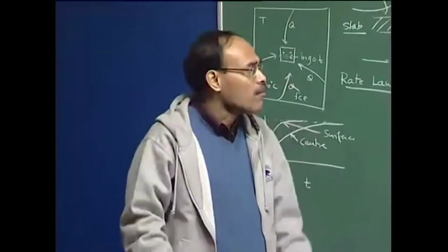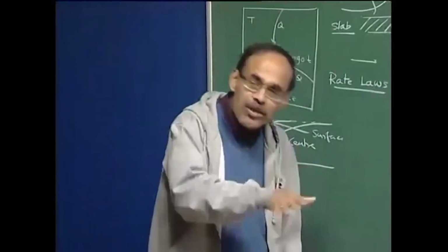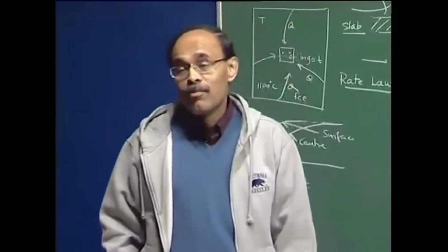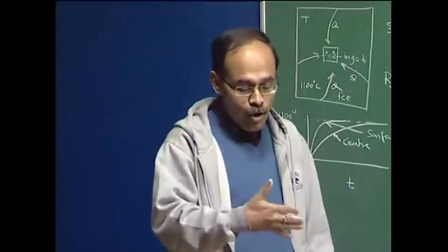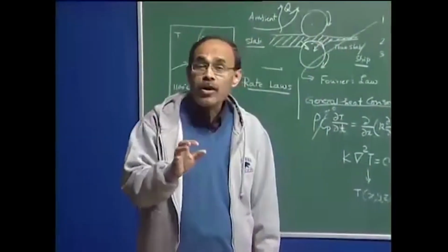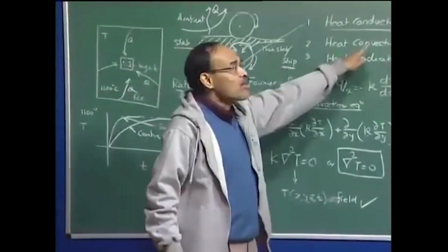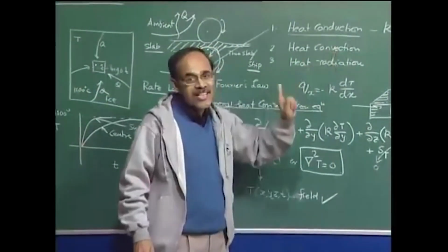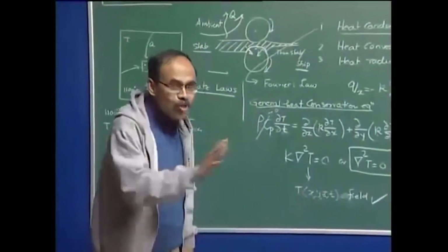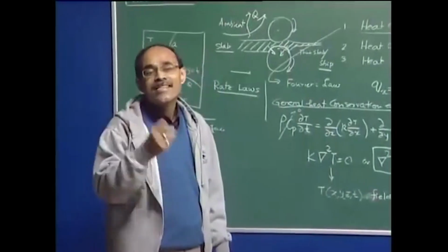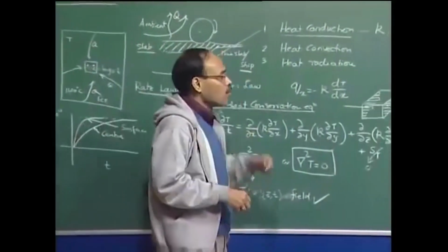You are feeling warmth very quickly, and this tells us that the speed at which the fluid is flowing is going to play a very important role in determining the rate at which heat is transferred from one point to another. So, before we can talk of convective heat transfer theory, we must have some knowledge of fluid flow. If you do not know at what rate the fluid is flowing, you will not be able to predict the rate of convective heat transfer.